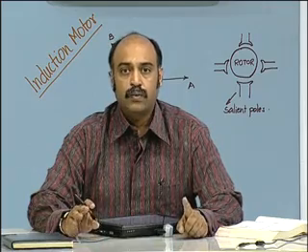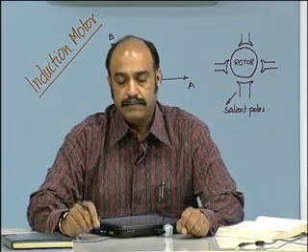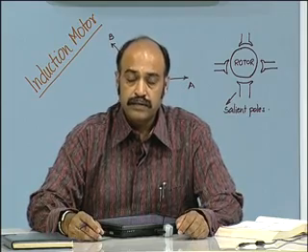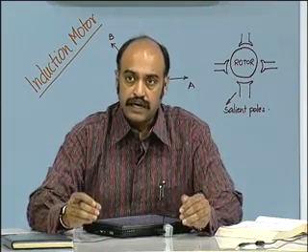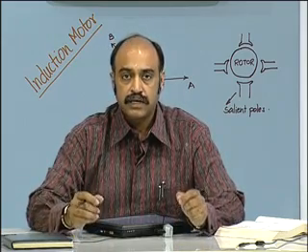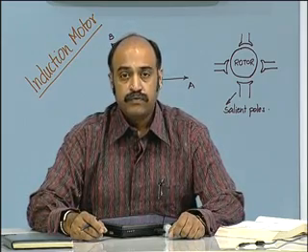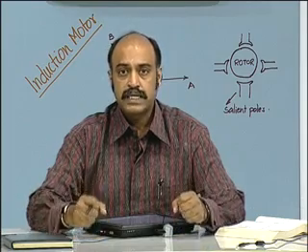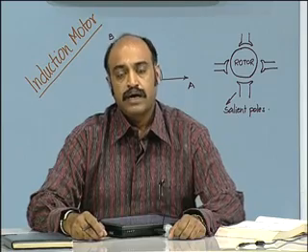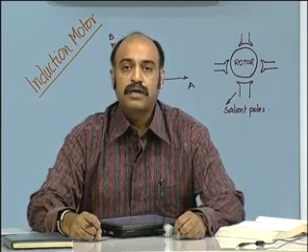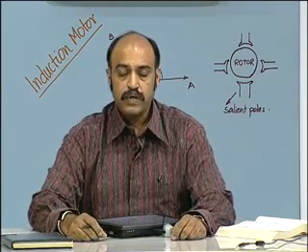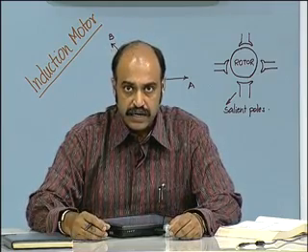However, they are 120 degrees apart in time. Now applying one more constraint, that is the currents from these three sources flow through coils in the stator of the motor, wherein the coils are physically located in space 120 degrees apart. A combination of these two produces a rotating magnetic field. So let us now see how this is created.